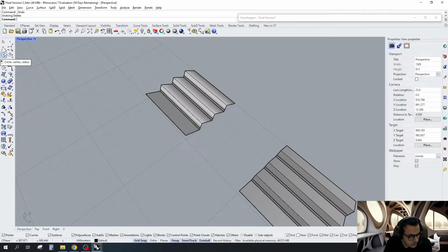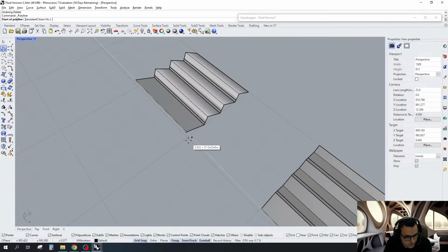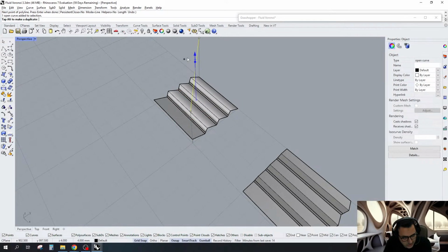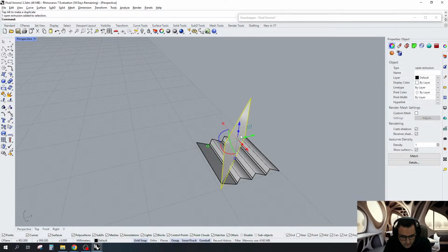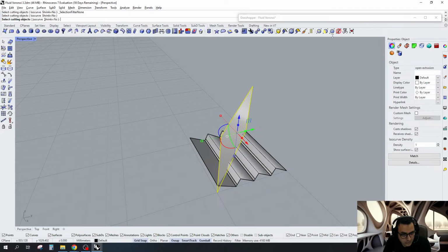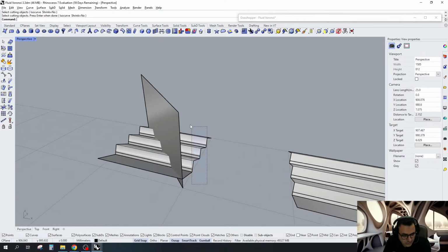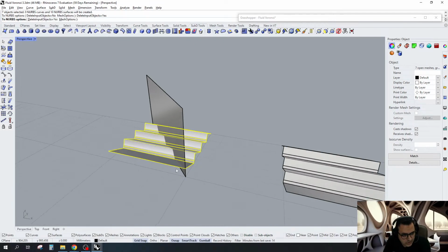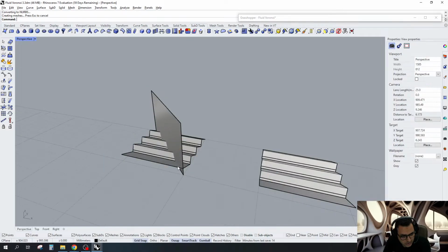So I want to create, let's create a line from this point to this point. And this line I want it to be extruded and I want this surface to be split by these meshes. It doesn't understand. We need to transform those into NURBS. So if I set to NURBS, delete input, yes. Okay, so now they are NURBS.